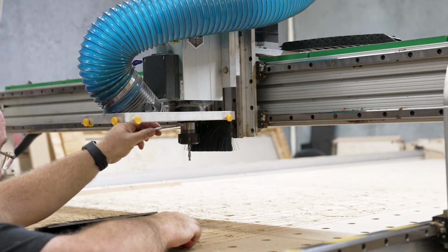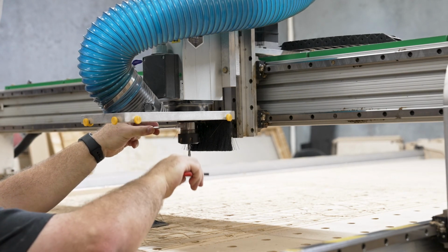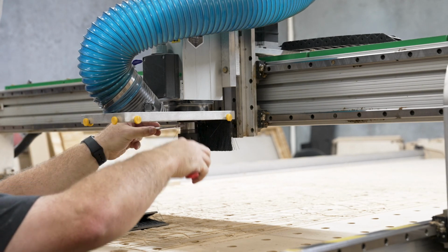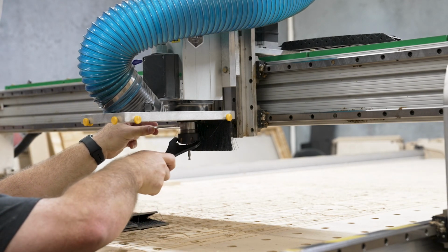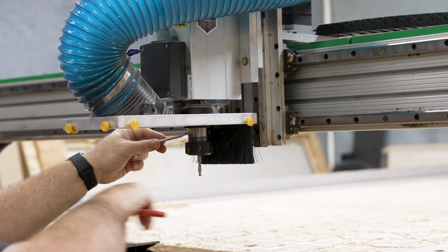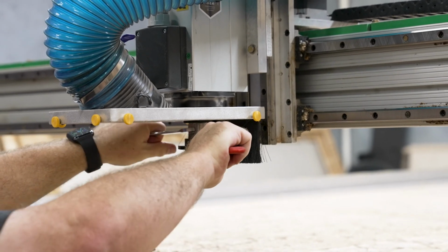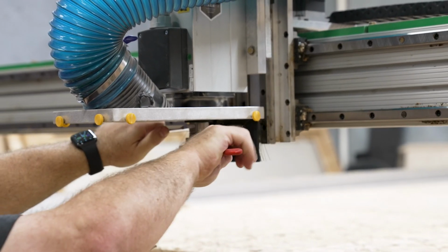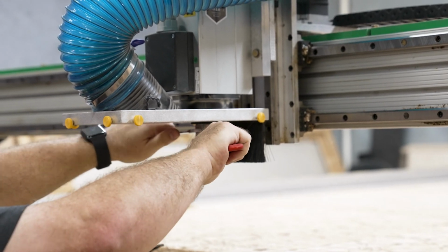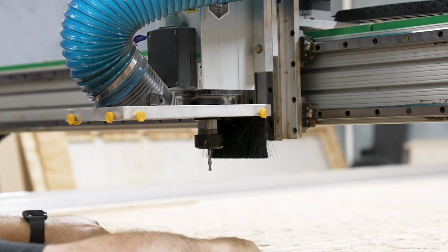Two tools. This tool holds the shaft of the spindle. This goes on the nut. Everybody's going to have a chance to do this. You want to bring this tool up from the bottom. It doesn't go on this way. That's not the right way to do it. You want to make sure that all 4 points are actually on the nut. And then it's opposite of what you normally would do. It's not righty tighty, lefty loosey. It's the opposite. And you press.